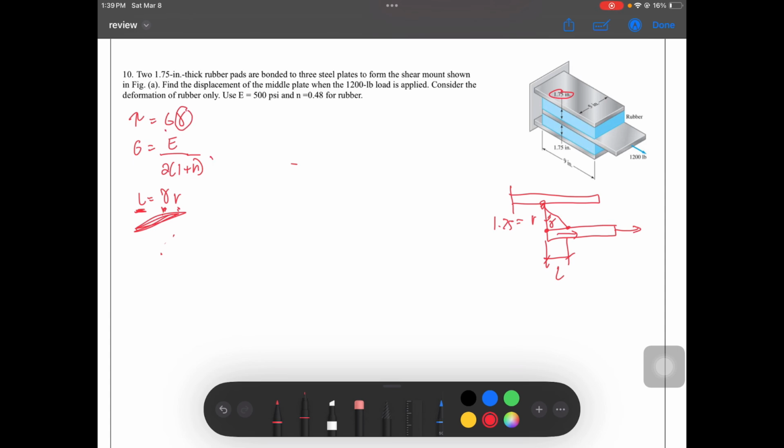We can get G with this equation since given ang E at N. Pero wala tayong shearing stress. Pero may formula tayo ng shearing stress. P over A din yun. So, paano ang P over A natin dito? Diba, ito yung P natin. But since dalawa, ito, so magta-travel ang ating axial, half pupunta doon, half pupunta dito.